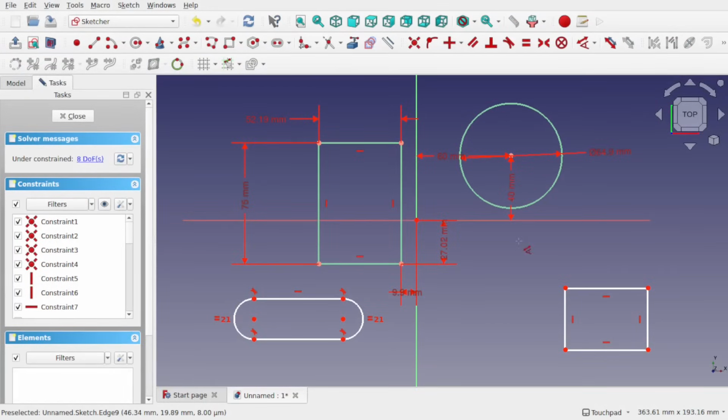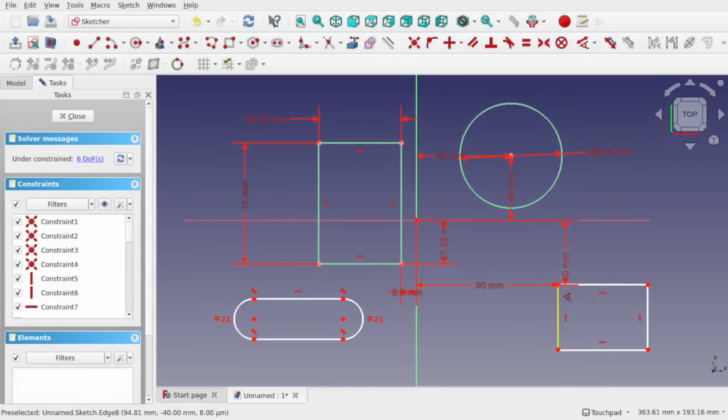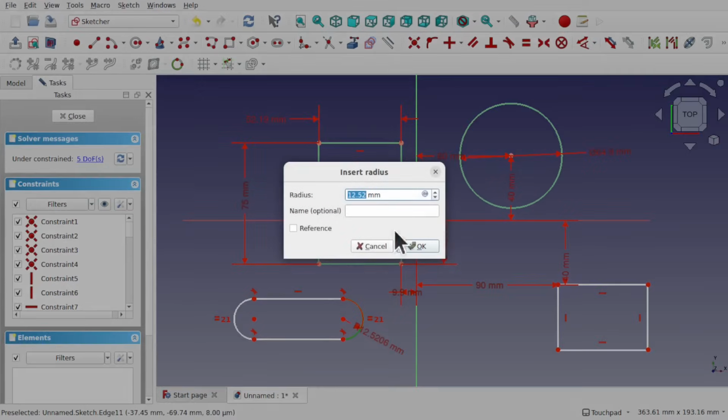So let's do that for this one. So click on this point, distance, horizontal length, hit M on the keyboard, and now we get the two lengths in there. So if I hit M again, single length, those different modes, M again for the two lengths. And when we click, we can enter horizontal length, hit enter, and vertical length. So that's the position of that point away from that center point. And it's quite easy to dimension as we go.